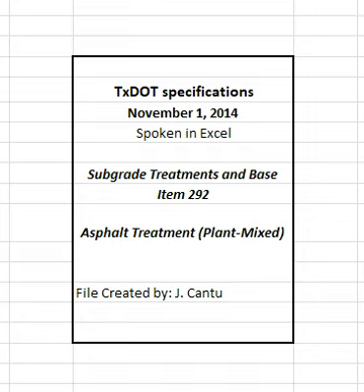If department-owned RAP is available for the contractor's use, the contractor may use contractor-owned fractionated RAP and replace it with an equal quantity of department-owned RAP. Department-owned RAP generated through required work on the contract is available for the contractor's use when shown on the plans. Perform any necessary tests to ensure contractor or department-owned RAP is appropriate for use.